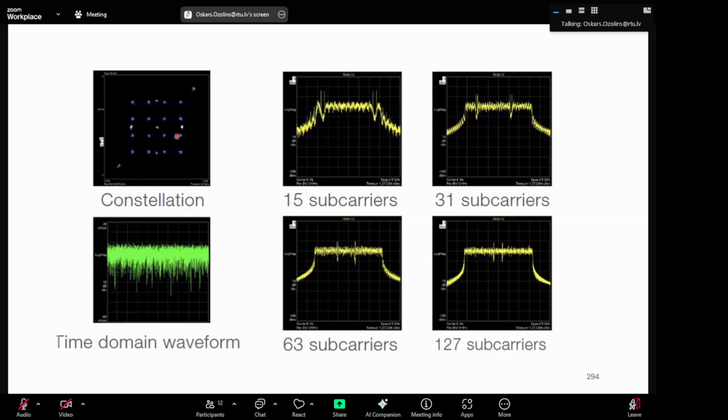So, for example, if you ideally have a very flat channel, then you can use the same constellation order for every subcarrier. But you can also use the principle called bit and power loading in OFDM signals, which allows you to increase the capacity even more if you have a bandwidth limited system.